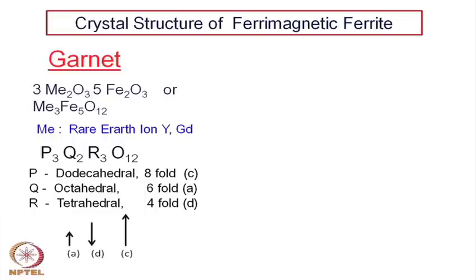One of the reasons we have discussed earlier, in a ferrimagnetic ordering, there is antiparallel ordering. The magnetic moments of the neighboring atoms have an antiparallel ordering, but because the magnitudes of the magnetic moments are different, they do not cancel each other, unlike in an antiferromagnetic material, where the antiparallel ordering and the magnitudes being the same, the net magnetic moment is 0.